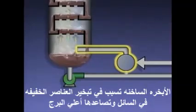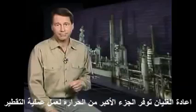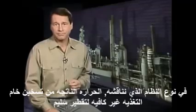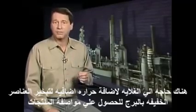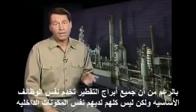The hot vapors cause any lighter fractions in the liquid at the bottom to vaporize and move up the tower. This reduces the amount of lighter fractions in the bottom's product. The reboiler provides the major portion of the heat that's required to make the distillation process work. In the type of system we've been discussing, the heat supplied by preheating the feed is not sufficient for proper distillation. The reboiler is needed to provide enough additional heat to vaporize the lighter fractions in the tower so that the products meet specifications.